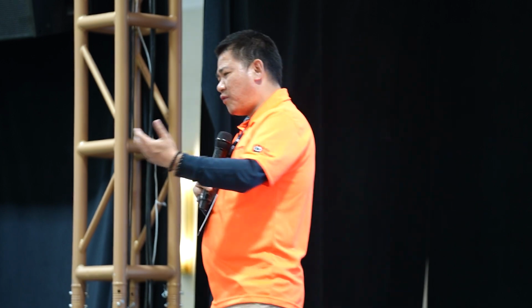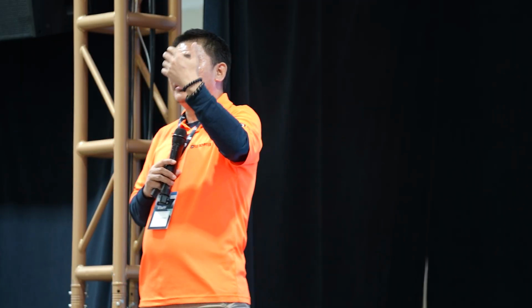So we again go back to basics. Okay, I can't go far, I can't go crazy with modulation. So what do I do? Again, go back to basics. Light has more properties. We only use amplitude and phase. There's also a property of light called polarization, right? And polarization is nothing but the direction of your electric field, right? In this diagram example, the electric field is on the vertical. So we call it a vertically polarized optical wave, right?